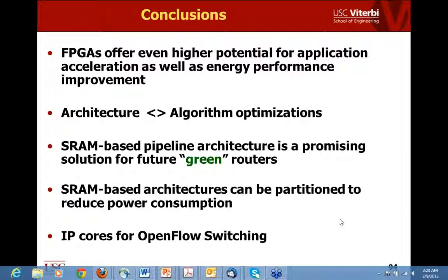So actually there are two questions. In the first portion of the talk, I am looking at them as data structures and mapping them into hardware. The mapping actually is a linear pipeline architecture, so I'm not really exploiting a particular feature of the FPGA. It is not something only FPGAs are good for implementing. In other words, I could have taken those architectures, built some SRAM, built a processing engine and the pipeline stages, and done them on ASICs also, for the IP lookup problem and the classification problem that I showed here.